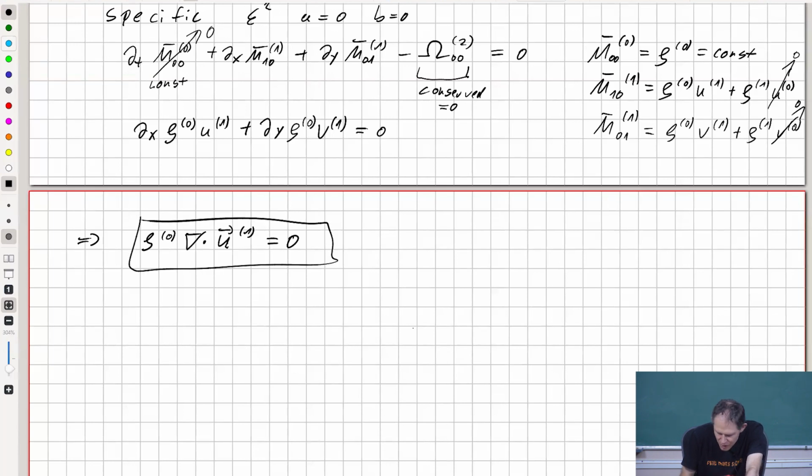Okay? Now, this is the first equivalent PDE that we observe, and we observe that this is the incompressibility condition. We see that under this scaling we get the incompressible version of the Navier-Stokes equation out. So the first equivalent partial differential equation we got.